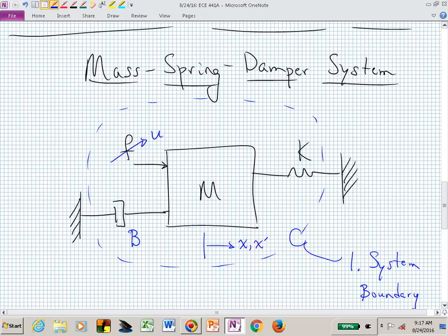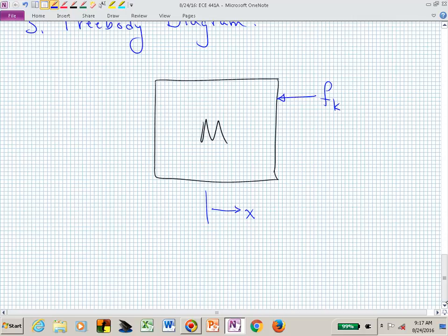Now if I move the mass to the right, what happens to the dashpot? Think of it really like a spring that has slightly different properties. So if I move that to the right, what's going to happen where that dashpot is located? It's going to try to oppose that movement, isn't it? So it will give us another force, F sub b.